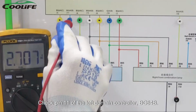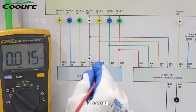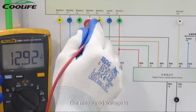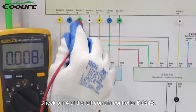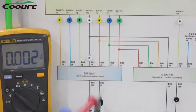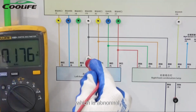Check pin 11 of the left domain controller, BG64B. The measured voltage is 12.9 volts, which is normal. Check pin 15 of the left domain controller, BG64B. The measured voltage is 12.9 volts, which is normal. Check pin 4 of the left domain controller, BG64B. The measured voltage is 0 volts, which is normal. Check pin B5/7 of the combination lamp. The measured voltage is 0 volts, which is abnormal.